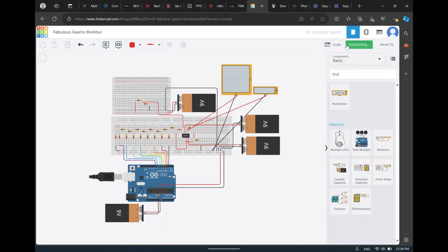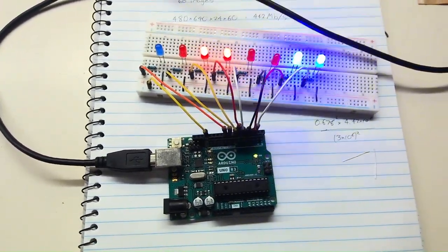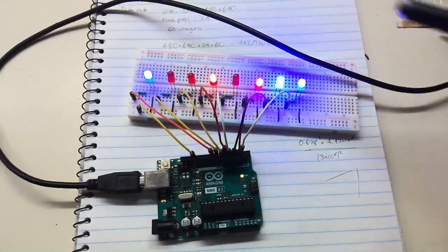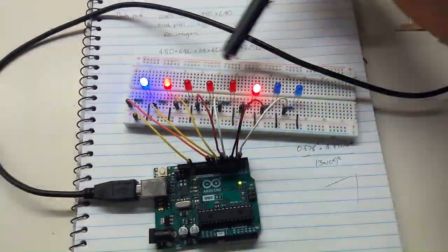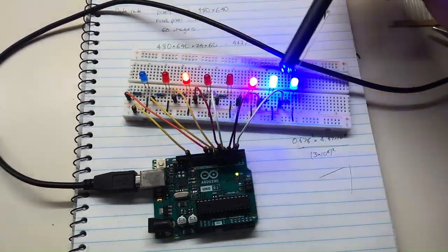If I run this code, you can see that we should get a beautiful sine wave that should have a frequency of 11 Hertz. You can't see it because of the refresh rate, but it's going from +5 to -5 volt. Before I connect my output pins 2 through 9 to the DAC, I just wanted to show you a quick visual representation of all the pins working properly. I've done this by hooking them up to LEDs.